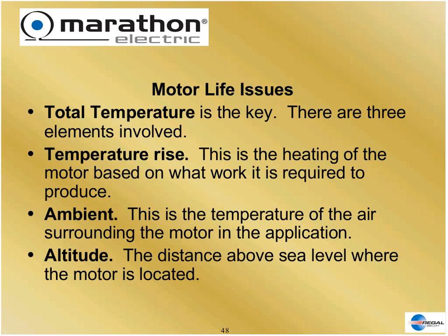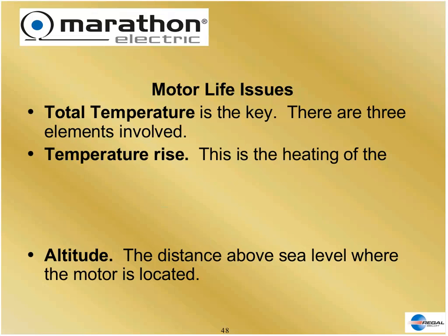The third thing is altitude. Marathon Electric is located in the Midwest. That's fine. But if you take a trip to Estes Park, Colorado, which is 10,000 feet up in the air, it is very difficult to breathe. The air is thin. The air is thin because it has fewer molecules. Having fewer molecules, it won't transfer the heat. The motor will get hot. The higher you go in altitude, the hotter the motor will get. That's a simple matter of physics.